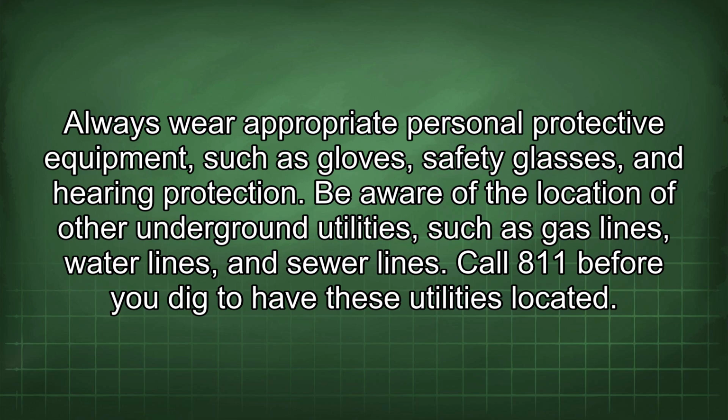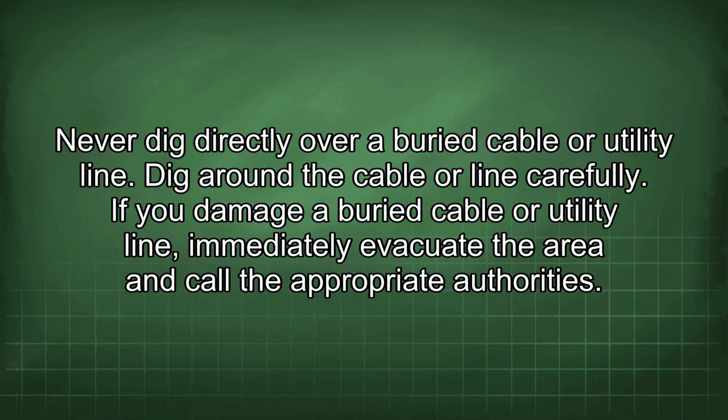Be aware of the location of other underground utilities, such as gas lines, water lines, and sewer lines. Call 811 before you dig to have these utilities located. Never dig directly over a buried cable or utility line. Dig around the cable or line carefully. If you damage a buried cable or utility line, immediately evacuate the area and call the appropriate authorities.